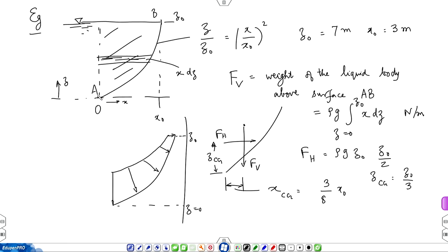So, why pressure distribution? Well, let us say the ground moves, then you are no longer in the domain of hydrostatics. Then you have to bring in fluid motion into consideration. Then these pressures will depend on not only the vertical coordinate, but also time. Accordingly, F v and F h will change with time, and their point of application will also change with time. Then it is no longer very useful to have effective forces for your description. You are better off staying with pressures.